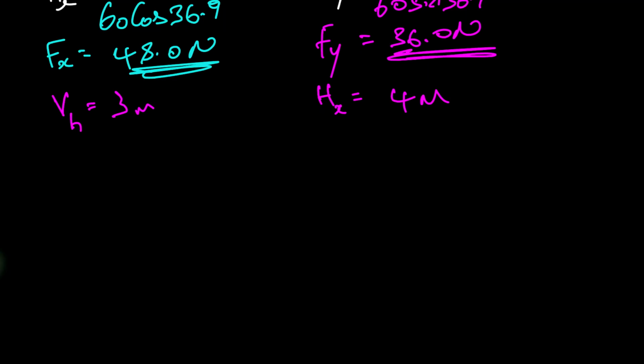And that's simply because the moment of a force is the force multiplied by the perpendicular distance. So if the force is acting horizontally, then it's the vertical distance or length that would be perpendicular to that. And we've already stated that these are measured from the origin already.